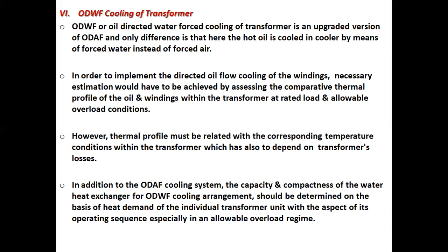In addition to the ODAF cooling system, the capacity and compactness of the water heat exchangers for ODWF cooling arrangement should be determined on the basis of heat demand of the individual transformer unit with the aspect of its operating sequence, especially in an allowable overload regime.